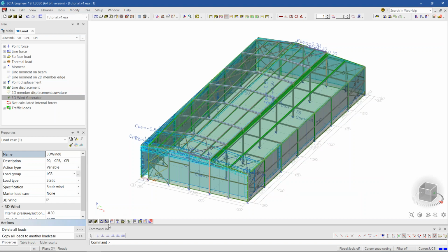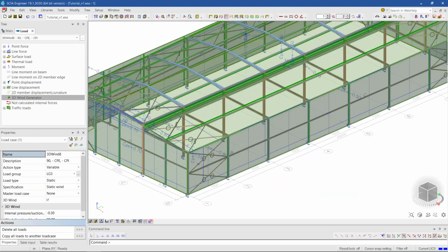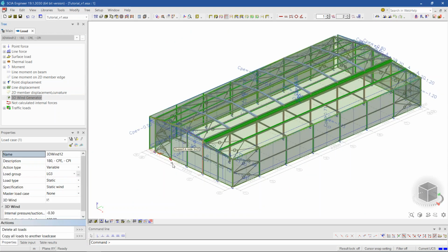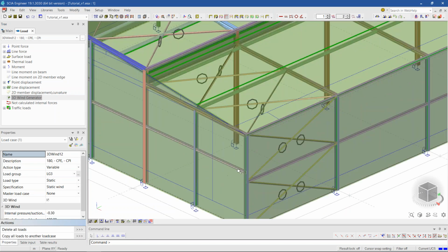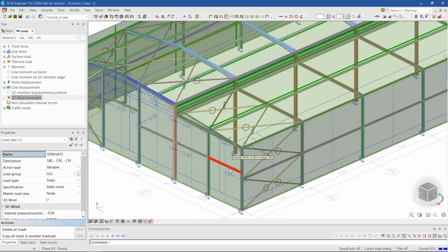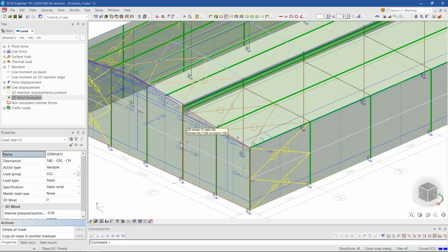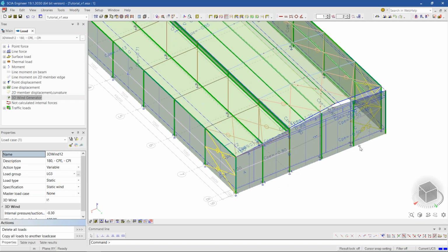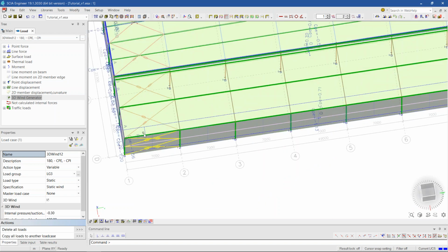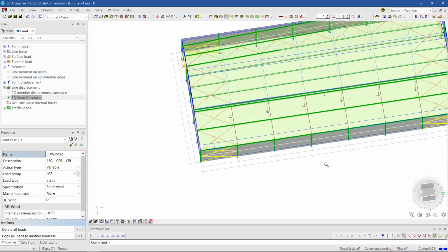What I want to show here is more or less what zones I've obtained from this approximation. So if we look at, let's say, wind from opposite of the x direction. So here you see zone D. Here are these little letters here, this is zone A and B. They're just behind. Wait, I will just do this. Zone A, zone B, zone C. And the same on the other side, zone A, B, C. And then on the roof, I have here the zone F and zone D and etc.